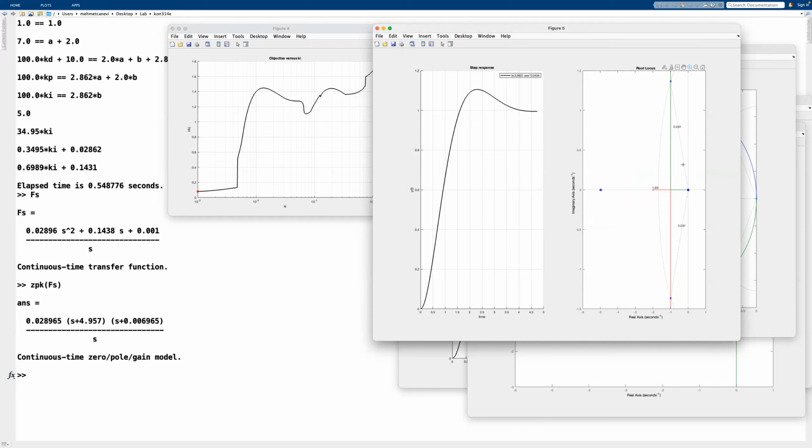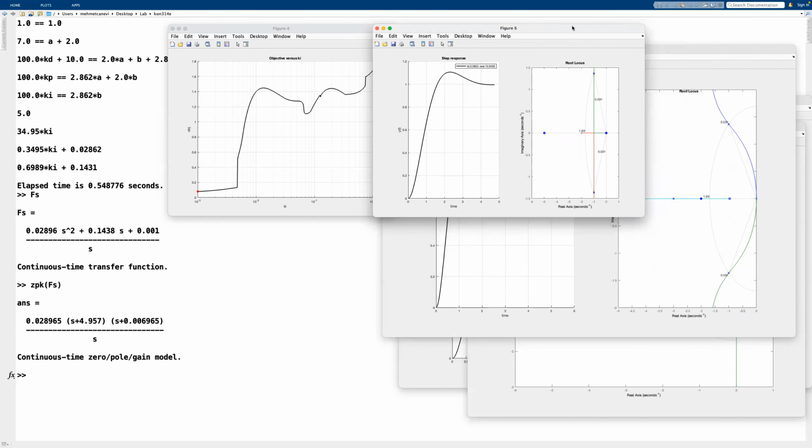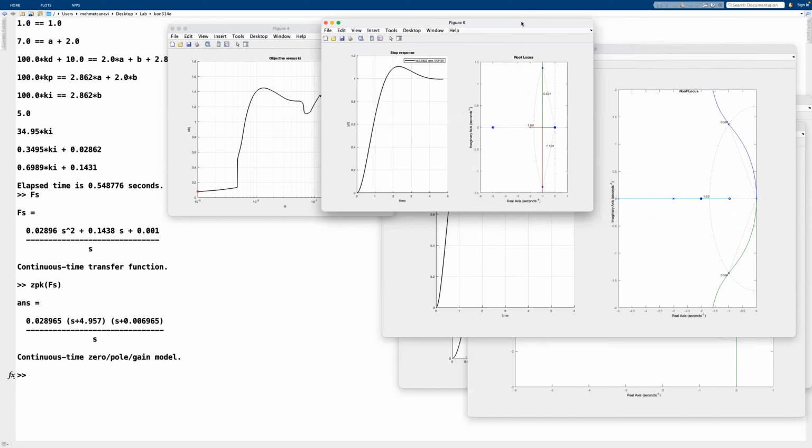but it might be something like an adaptive control strategy or something like that. Then maybe pole zero cancellation is not that big of a deal. But usually you should be careful about this, and you don't want to be near the vicinity of the j omega axis because that's the most dangerous version. On the right half plane, you never pole zero cancel anyway because that's not possible, and it will definitely be unstable. So yeah, but you can see sometimes you have to do what you have to do. You have to cancel out the poles, and there we go.